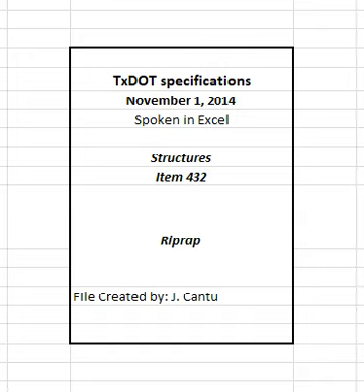2.3.1 Type R. Use stones between 50 and 250 pounds with at least 50% of the stones heavier than 100 pounds. 2.3.2 Type F. Use stones between 50 and 250 pounds with at least 40% of the stones heavier than 100 pounds. Use stones with at least one broad flat surface. 2.3.3 Common. Use stones between 50 and 250 pounds.